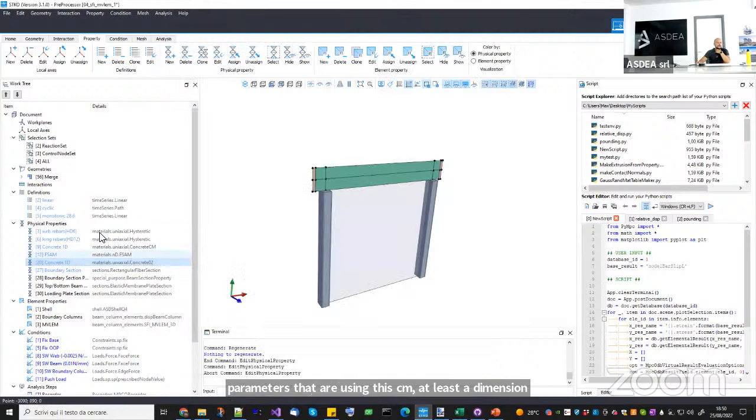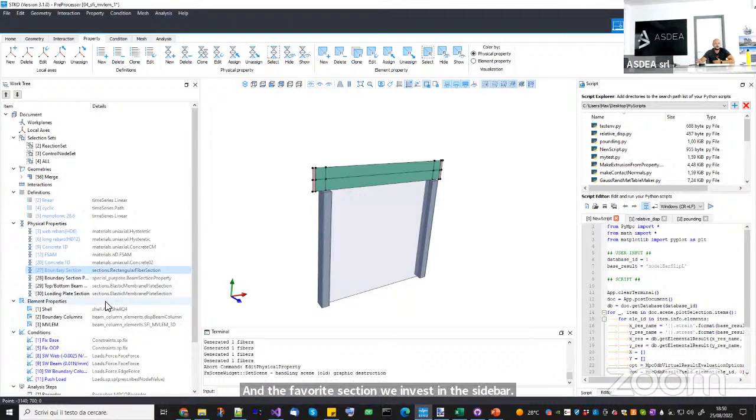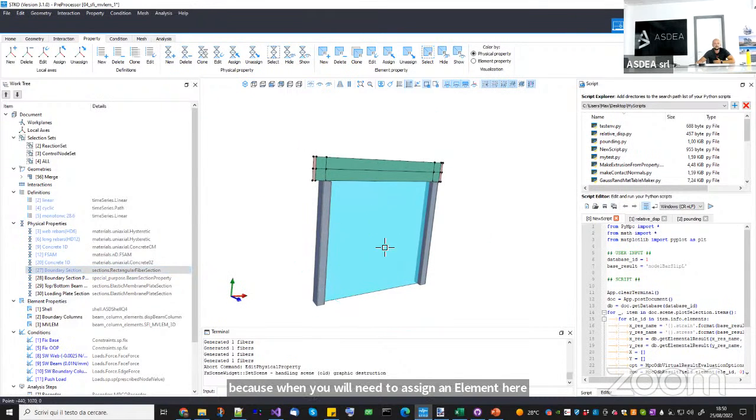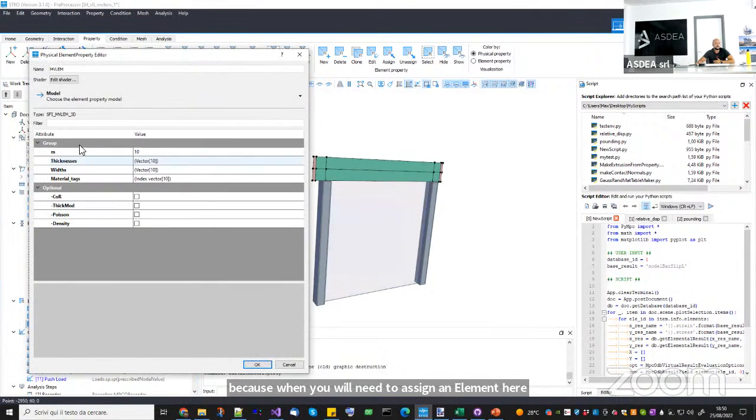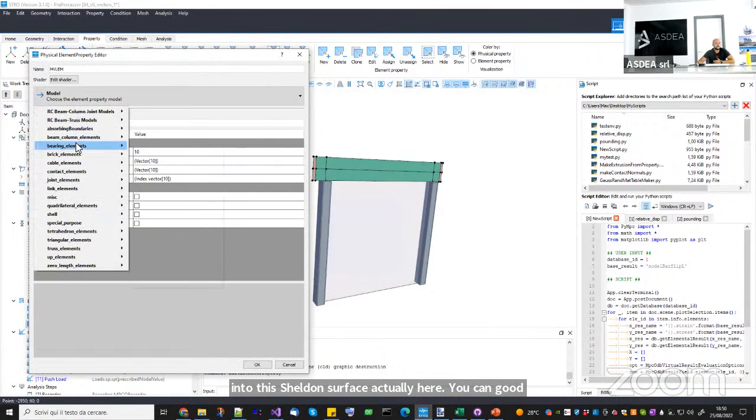And then this concrete plus the 12 diameter rebars go into the fiber section here. The fiber section will be assigned to the side boundaries. Now, I just realized that it's not completely necessary, because when you need to assign an element to this shell surface, you can go on the elements and find it under...